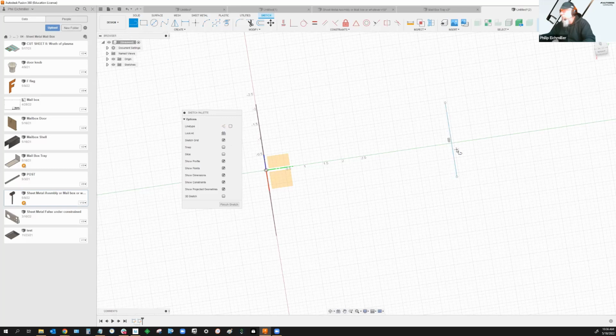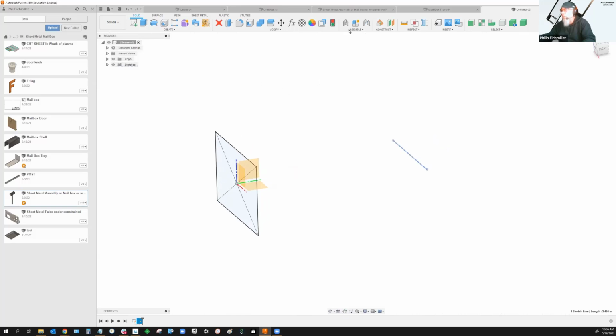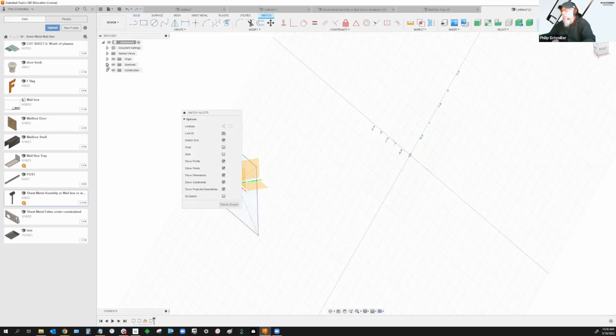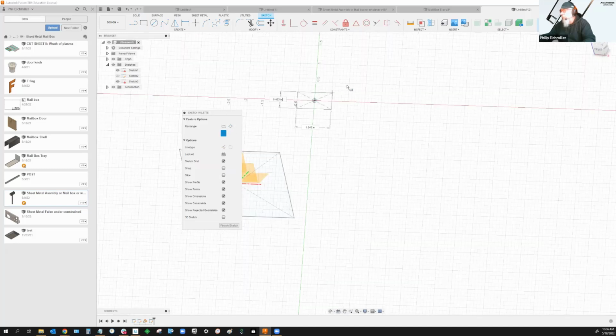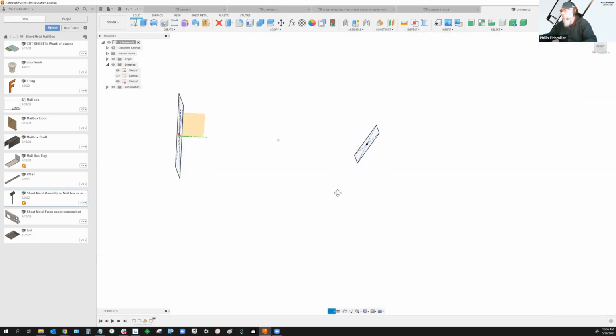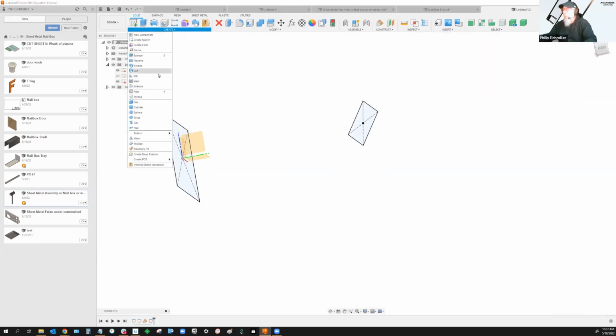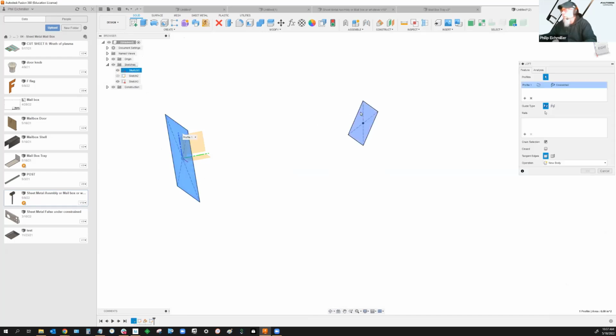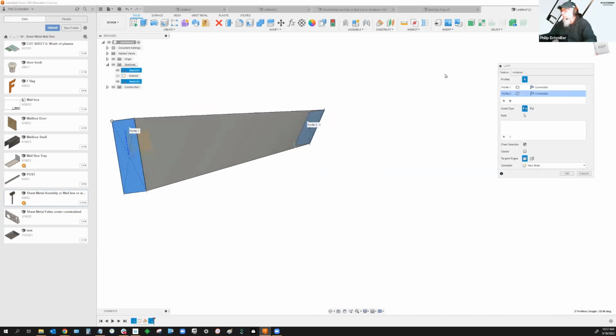So I'm going to put in a construction line on this sketch here to serve as an axis for another plane, and then put this at a slight angle. Go ahead and make a sketch on it. Turn off that axis sketch. And let's make another rectangle here. We'll make this 2 inches by 1 inch. So now we definitely have the need to loft in order to get these two things to talk to each other. Now, lofting between here and here, right? That's pretty straightforward.